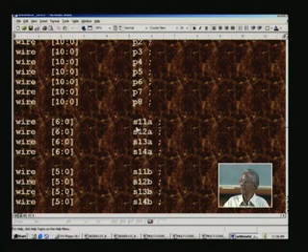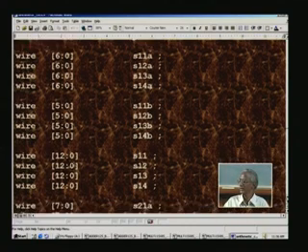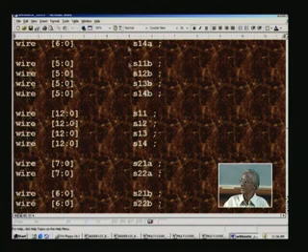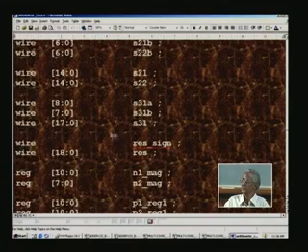So is the case with the first stage addition, where we have seen S11 through S14, which are here. There are also combinations to start with, especially the LSB portion and even the MSB portion, which will primarily be assign statements, and later we will register them in the succeeding clocks. You can see so many signals are used here for the first stage, this is for the second stage, and this is for the third stage.